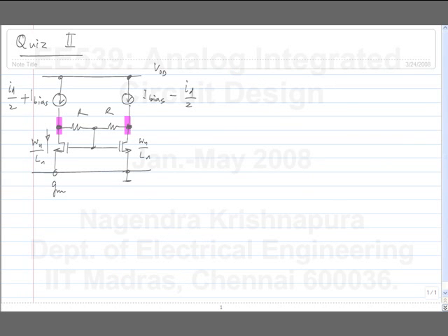In the third case, the excitation applied is in common mode, not differential. In this case, you connect the corresponding nodes together, form the common mode equivalent circuit and find the answer. So the common mode equivalent circuit will be just the incremental circuit with 2 ICM driven into a transistor.